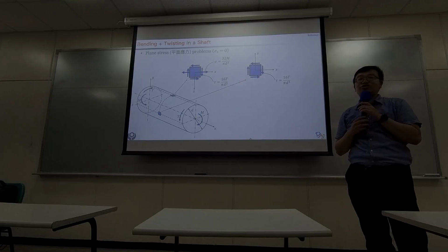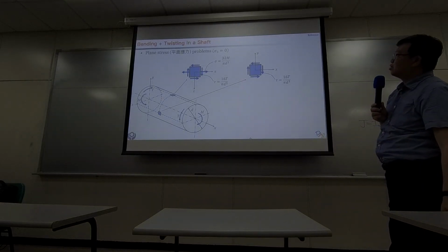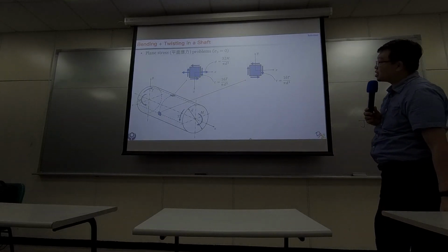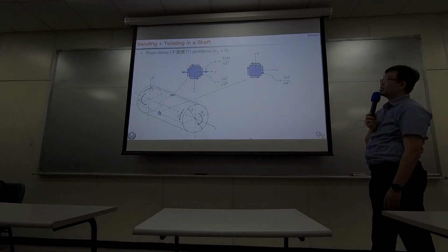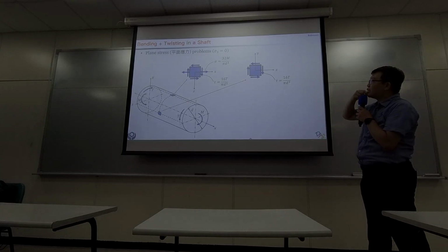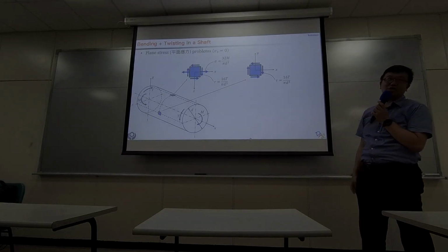And how large are those normal stresses and shearing stresses? Basically, you can just apply the equations that we derived earlier: 32 M over pi d cubed and 16 T over pi d cubed.